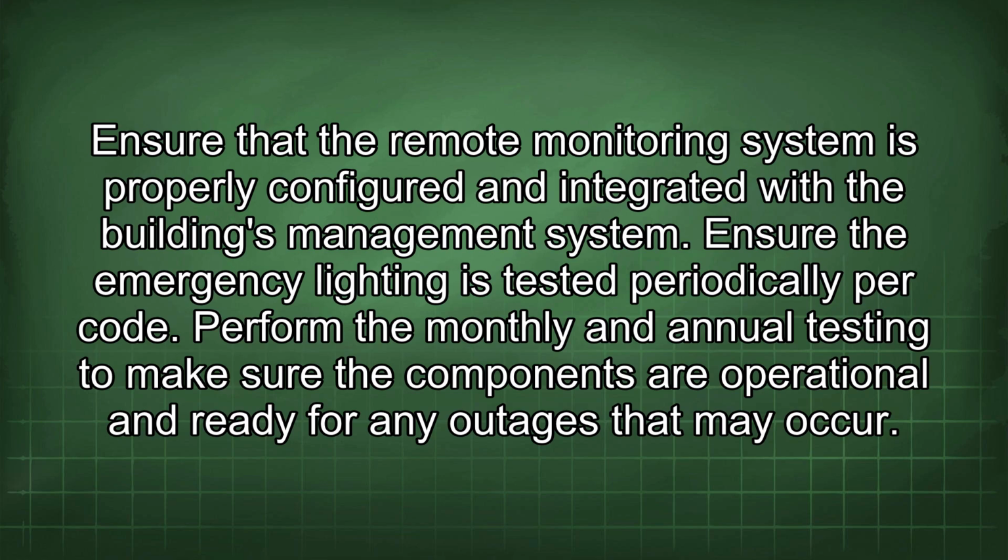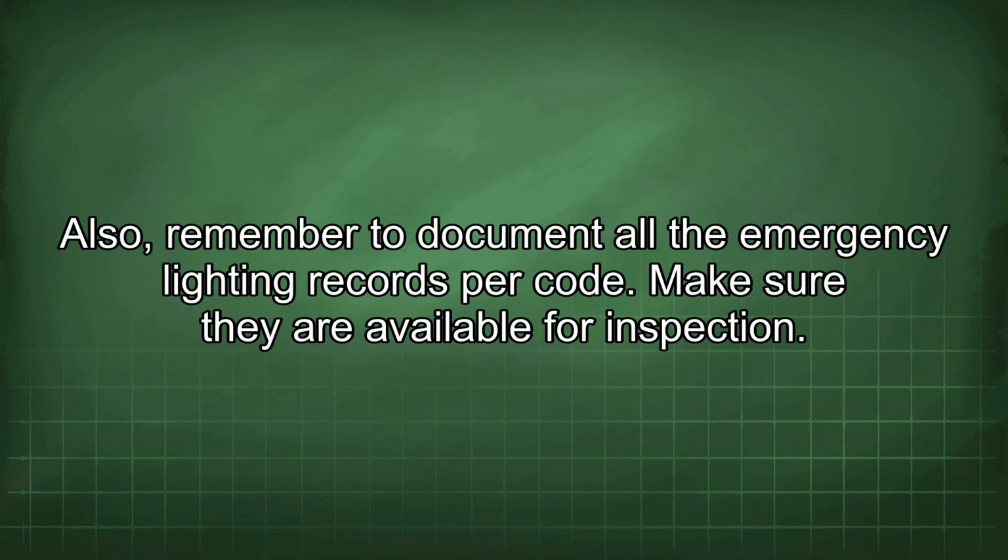Ensure the emergency lighting is tested periodically per code. Perform the monthly and annual testing to make sure the components are operational and ready for any outages that may occur. Also, remember to document all the emergency lighting records per code. Make sure they are available for inspection.